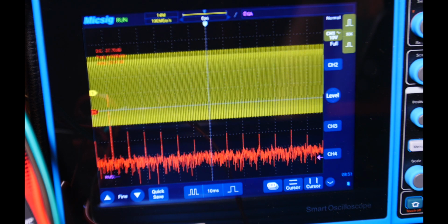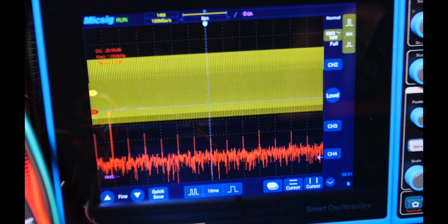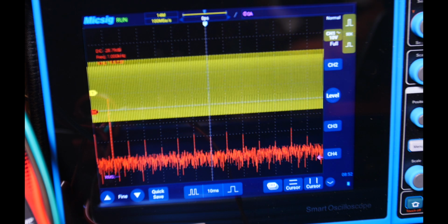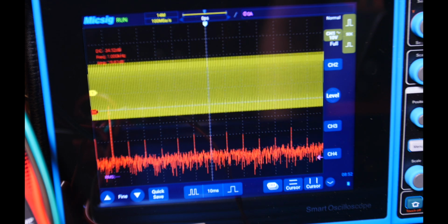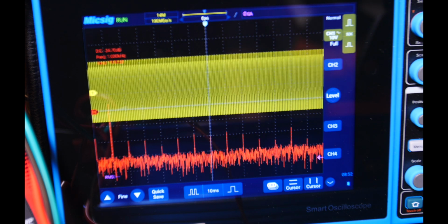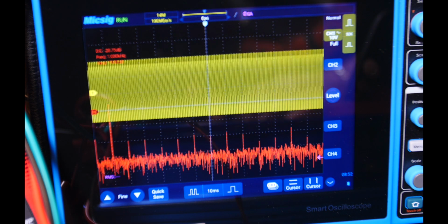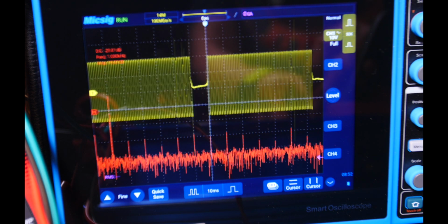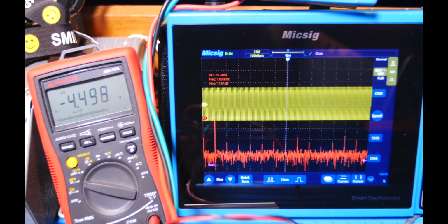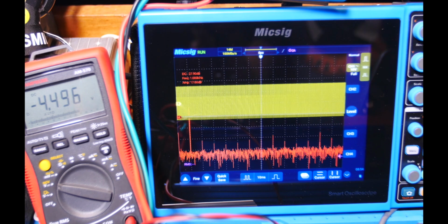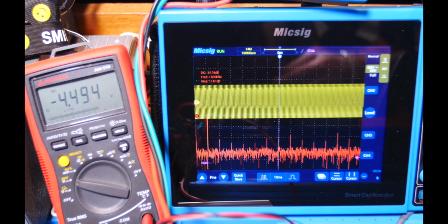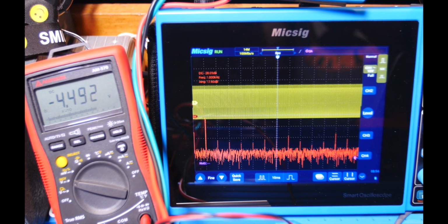We're at 1.4 volts RMS, but the red light on the power supply is on. Right there we're at 1.3 and it is just barely off. If I drop it down, the harmonics don't look any better, so at 1.3 I think we're safe. And then going back, adjusting that signal again. Yeah, again, I think when we get about 4.5 volts with this power supply rail and the combination of things going on, that's about the optimal level at this point.